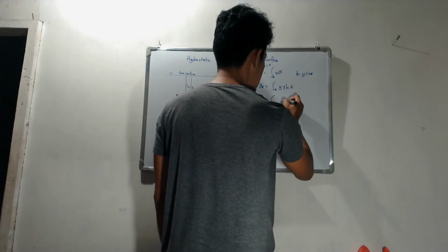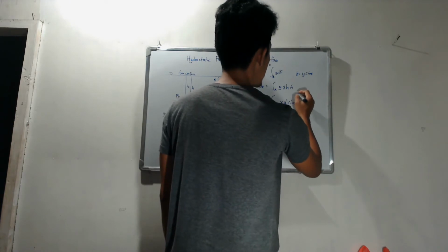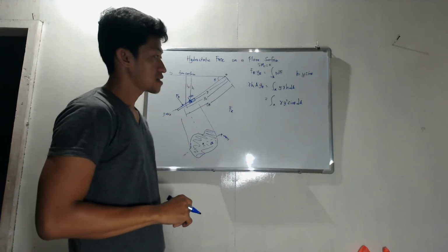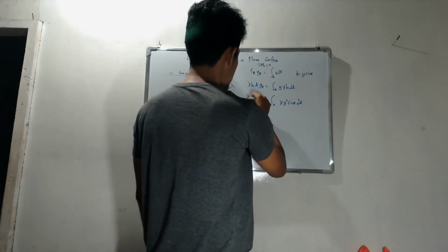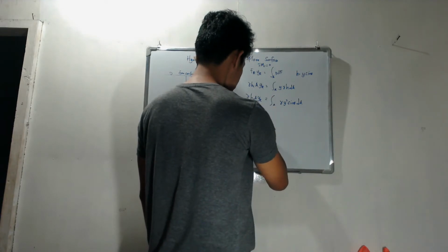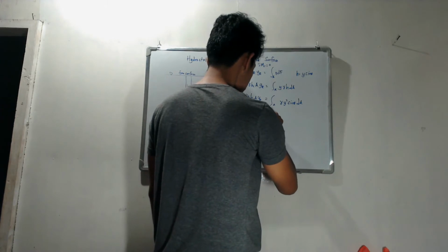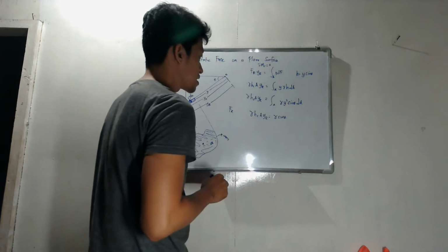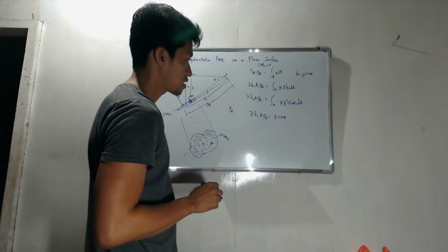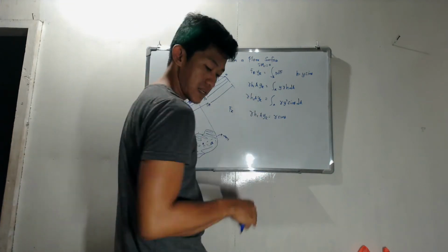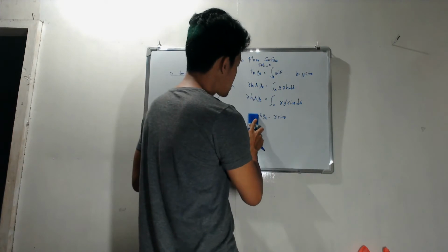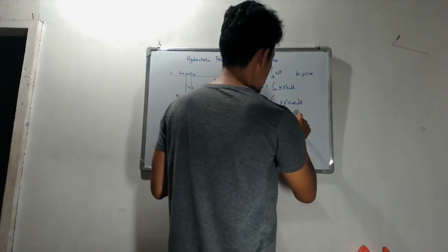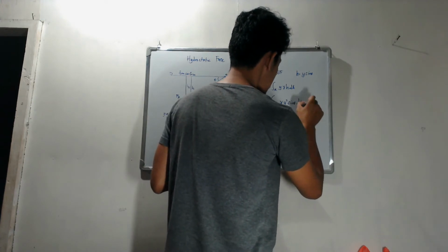Therefore we have gamma y squared sine theta dA. Taking out the constants, gamma sine theta, but then h sub c is just gamma y c sine theta, integral of A y squared dA.